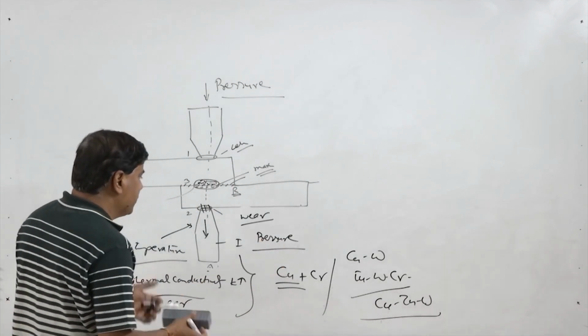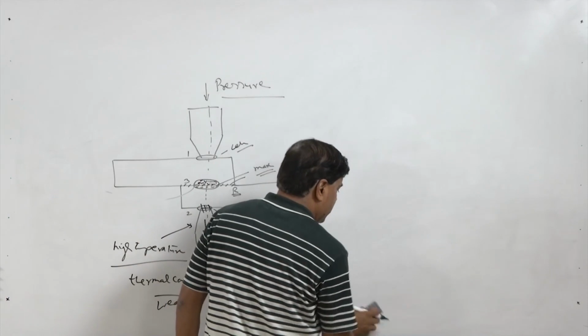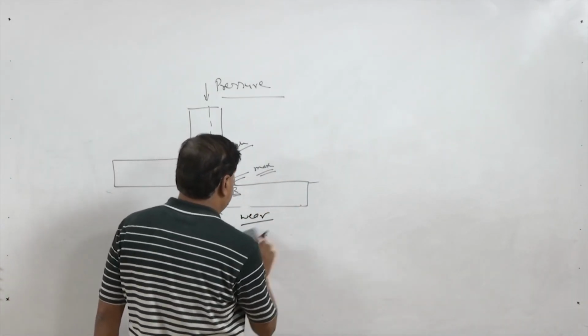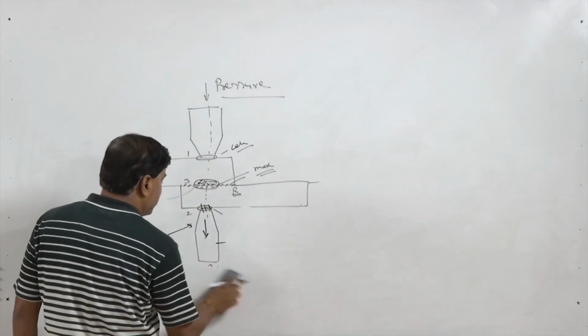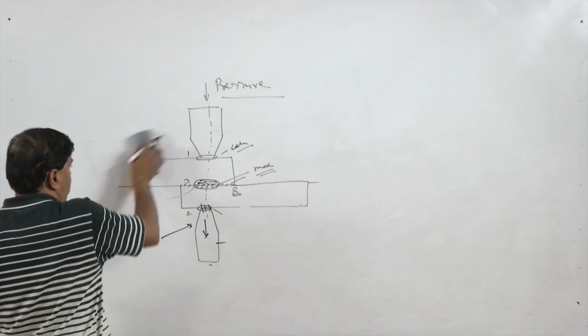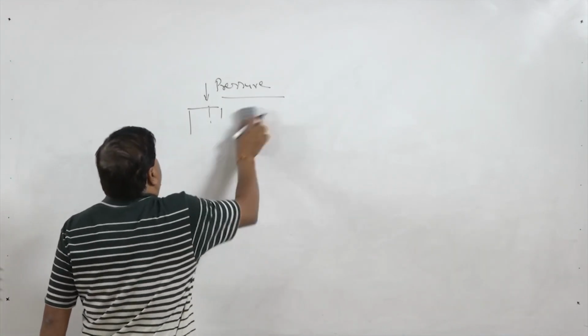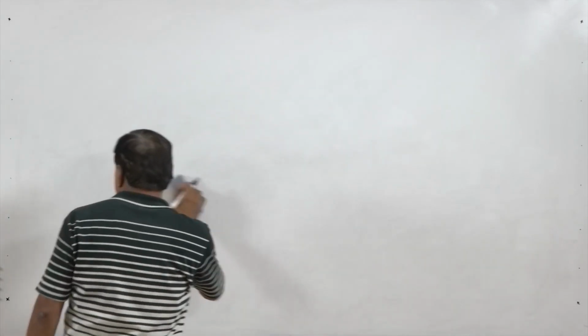These alloys offer very good resistance to thermal softening, good wear resistance without much compromising on the electrical conductivity of the electrode. However, alloying will definitely reduce the thermal conductivity as well as electrical conductivity, but they provide enough value of these properties so that they can be used effectively for the purpose of developing the joints.